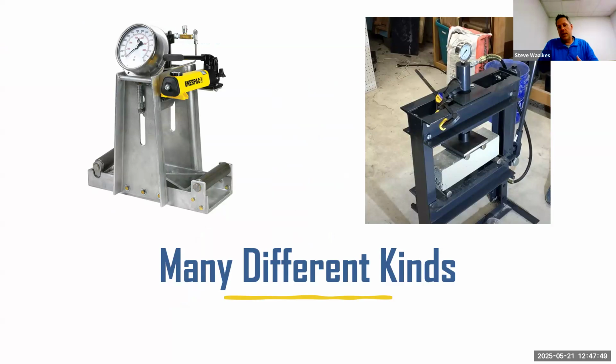There are a lot of different breakers out there as far as compression machines, and what we see here are the beam machines. The one on the left, we have one of those. That's a center point loading machine, versus the one on the right. The load in the middle, you can see, is split into two. There are two rollers underneath that plate, located at the third points. So they're 6 inches apart, and they're 6 inches from the supports on the bottom, which are at 18-inch spacing. And that gives a third point loading.